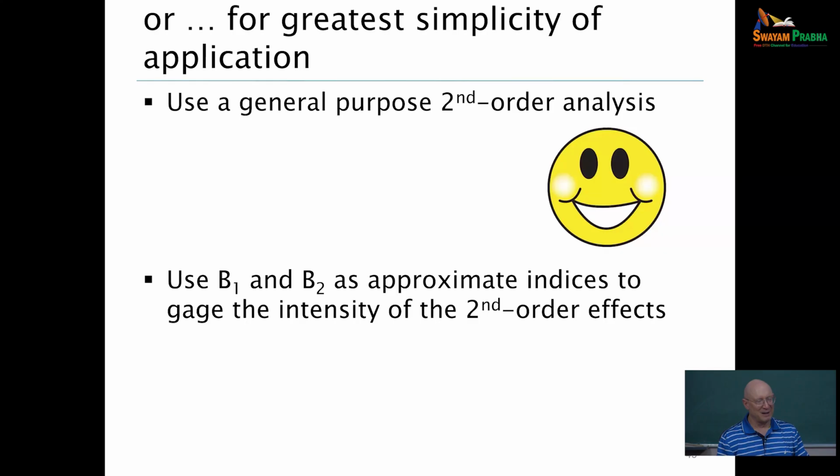Well, again, they give us some indication of how the frame is behaving. So they're still useful in that respect, but easily at this time in our profession, second order analysis is relatively ubiquitous for frames. And so, okay, use it.